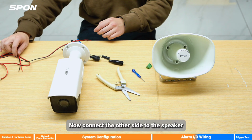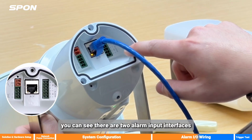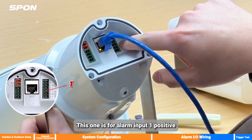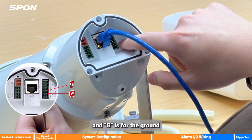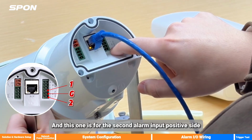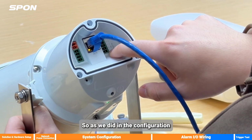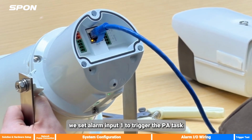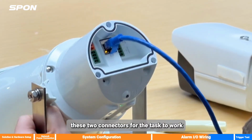Now to connect the other side to the speaker. For the speaker, you can see there are two alarm input interfaces. This one is for input 1 positive, and the G is for the ground side. And this one is for the second alarm input's positive side. As we did in the configuration, we set alarm input 1 to trigger the PA task, so we just need to connect these two connectors for the task to work.